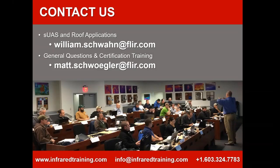Exactly, Matt. It's not always cut and dried. It has to do with a lot of things. And one of those things is, hey, do I have cloud cover? Cloud is an insulator to the sky, which means that I'm not going to get the delta T I need, even though it is well after dark. Or maybe I have a cool, clear sky, and the sun just came off the structure and there's no solar impact on the structure anymore, I've gotten good results. And it isn't even after that 30 minutes after solar sunset. So, the thing to keep in mind is it's not cut and dried. It's experimental, and it's challenging. So, I've done it at 4:30 in the afternoon. I had a 10-story structure on one side. I was working on a 3-story structure, and that roof no longer had direct solar impact, and I've had results. So, like you said, Matt, it's just not cut and dried.